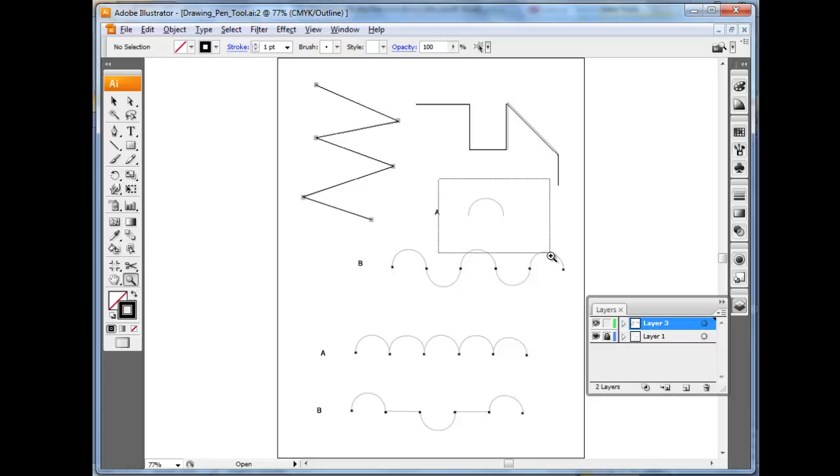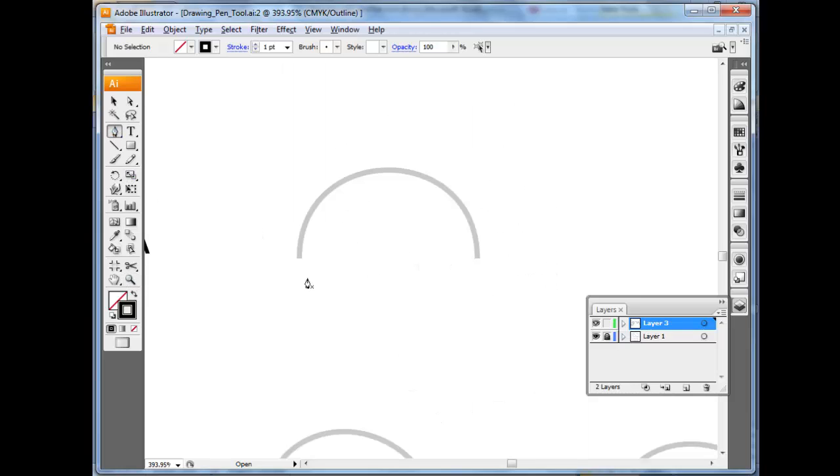Bezier curves. This first curve goes up and then comes down. So I'm going to click here. Holding the Shift key down locks me so I'm vertical, and I'm going up. And then I'm coming down. So I'm going to click over here at the end and run down. Hold the Shift key. Now that might seem kind of obvious, but let's undo that.